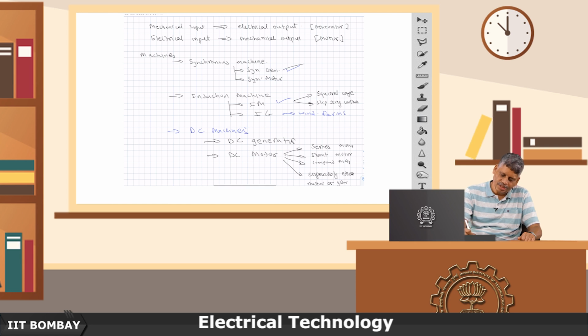And in synchronous generator, we have already seen that you have a 2 pole machine, which is usually called an alternator, and this is usually used with thermal or gas turbines, which create high speed. Or then you will have multiple poles, like 8 to 10 poles or 4 poles, always an even number of poles. These are usually low speed machines which are used for hydro, etc. So, here in a sense you are talking of high speed and low speed.